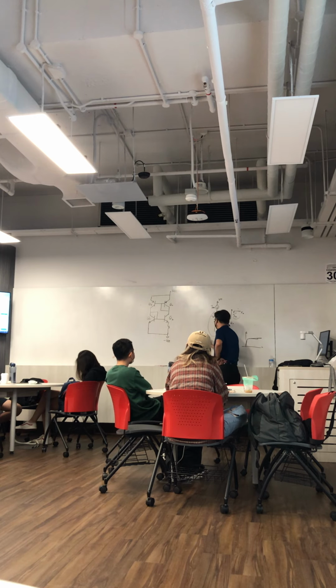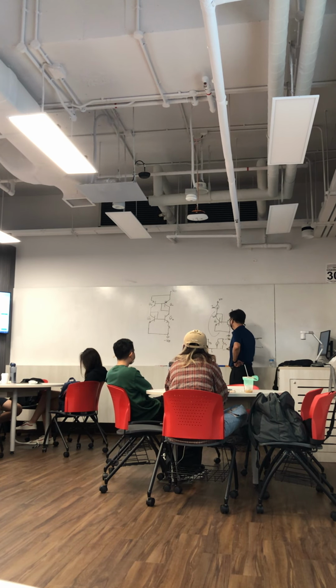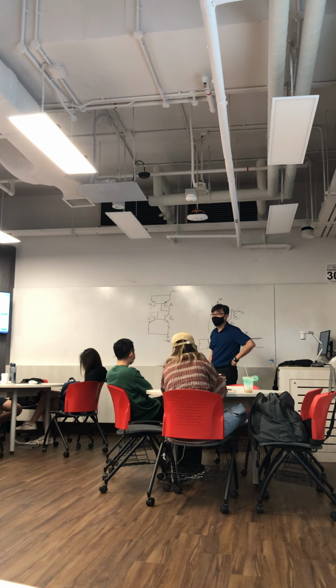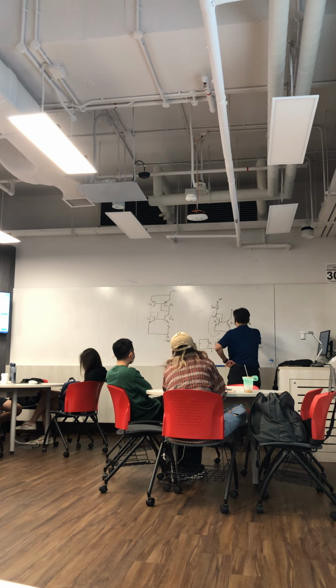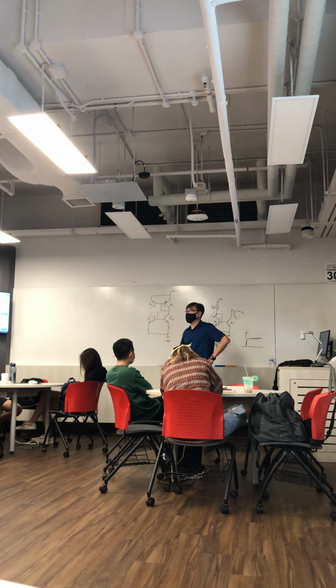or your emitter resistance in your lab, RE. So then this guy base is here. Then you have your r pi. Then at the output there you have the dependent current source, right? Then you want to measure the resistance here, you switch off the signal anyway, there's no current flow. Then this guy is open circuit, you see only R out. That's why this guy is only R out, right? Got it?